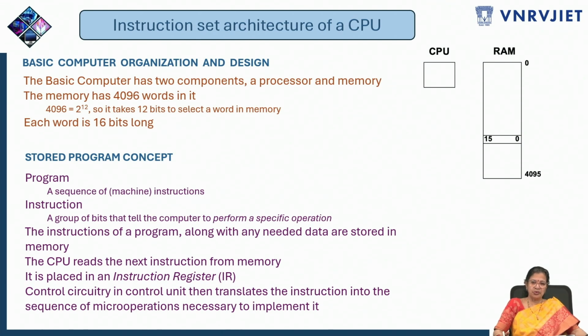Something like if you want to transfer a byte of data from memory to one of the registers, it will be divided: it should first be transferred into the bus structure and then into the specified register. In that way they are divided and then implemented. Whichever hardware modules need to be activated, the corresponding control signals will be generated by the control unit.